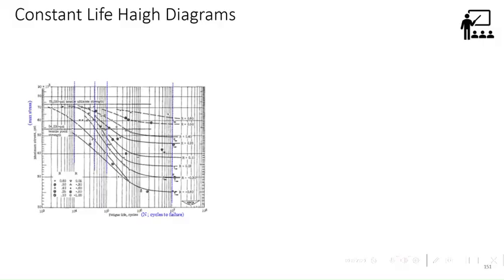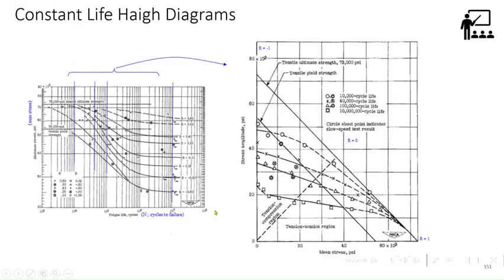So you generally have an S-N curve, because earlier this S-N curve is the material property, and they generated some chart of this. This is what the S-N curve is: either S max or stress amplitude versus number of cycles. But you generate a constant life diagram between the stress amplitude and mean stress, in line with what the Goodman equation we found. Here S max is there, different R is there, so one can convert to stress amplitude using the equation, and the mean stress we can get as well.